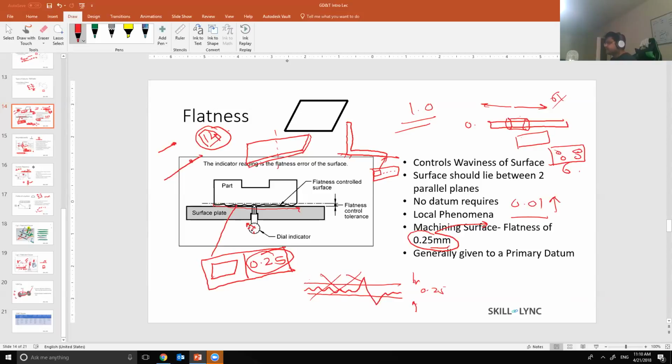I understand there are ways to get this number using a statistical method, the RSS. It's kind of complicated, and there are Excel sheets called RSS Excel sheets. It's as simple as 1 squared plus 2 squared plus 3 squared, and then take the root of those numbers to get this number. But in this specific example, I meant the worst case, that is the extreme case. All right. Thank you, Prasad.